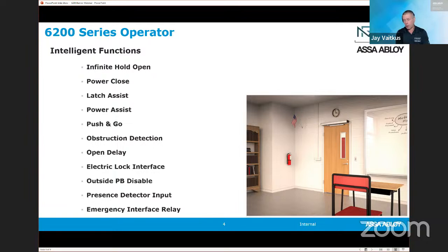And when used with an electric strike, you'll get some settling, or again, that wind and stack pressure. And when the activation button's pressed on the wall, the strike could be side loaded. And of course, the system will not be damaged, but just won't function the way the user expected. So it's a nice feature to be able to turn on, which will pull the door momentarily, a split second, in towards the frame, releasing that side load on the electric strike, and then go ahead and power open.